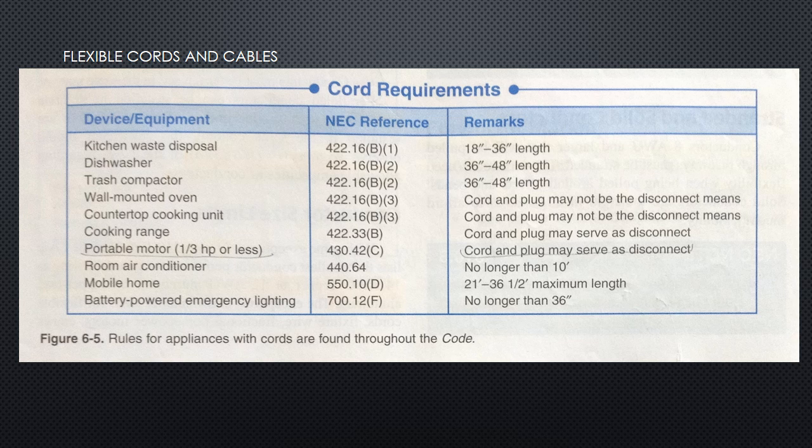Cords and cables may not be used as a substitute for permanent wiring. Generally, they may not be concealed, be permanently attached, or pass through walls, floors, or ceilings. They should be continuous and unspliced and should not be used as taps. Cords generally do not require a separate overcurrent protection device. The branch circuit fuse may serve as the sole protection for the cord.